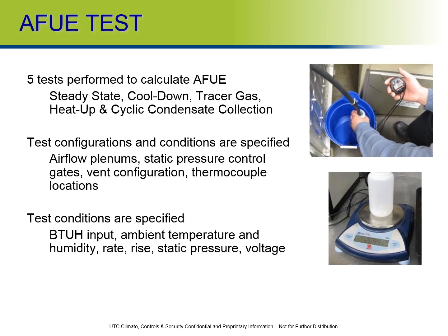They're not dealing with things that we deal with in the field, like different types of plenums and static pressure control. When you install a furnace into an application that may not be quite up to par on the ductwork size, which increases your static pressure, it directly impacts the amount of airflow through that system.